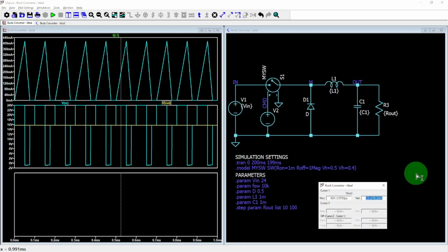In conclusion, when the buck converter operates in DCM, the output voltage tends to spike, which is not desirable. There are ways to mitigate or avoid DCM, and we'll cover some of those in the next few videos.